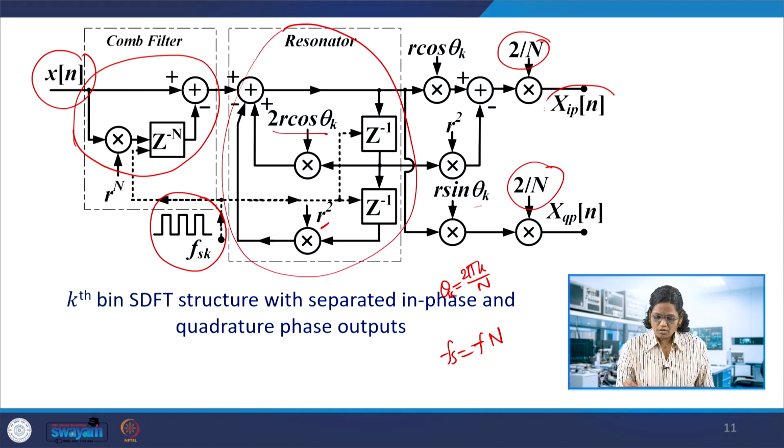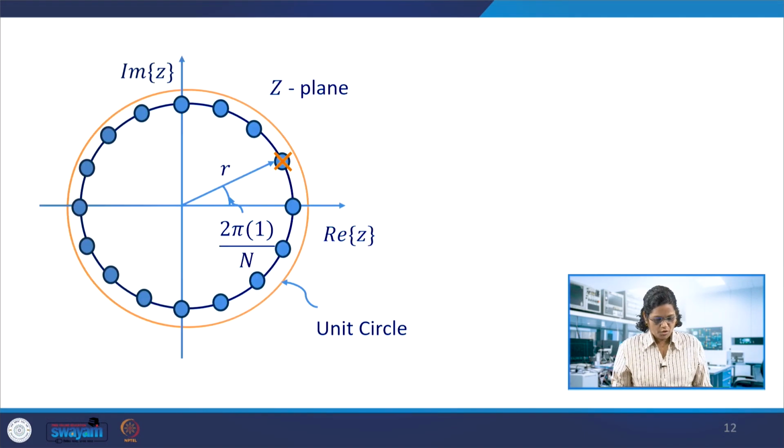So this gives out the in-phase component from the signal. If the signal contains fundamental, first, second, third harmonic and noise, this noisy signal can be passed on to this filter to get the in-phase and quadrature components. Here you will get the sine, and here you will have the cos, actually you get the minus cos here. So we will see the pole-zero diagram of this.